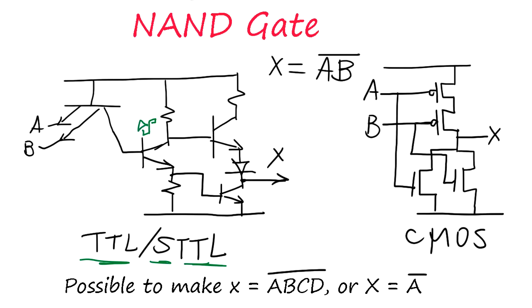will be here and holding this point so that transistor doesn't get saturated. Sometimes we write the transistor like that because the Schottky diode is integrated into the transistor. So what happens is if one of them goes low, this pull down here turns off, so this goes up and output becomes high, right? So only one of them makes output high. That's a NAND gate.